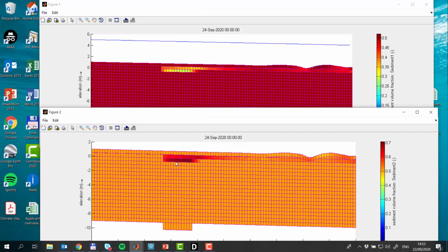So by doing these types of simulations and keeping the bookkeeping layer on inside the bed of a canal or a coastal zone or river, we can see what has happened inside the bed, which materials have moved from where to where.